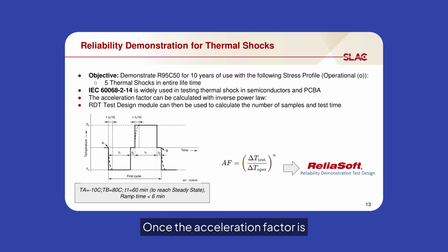Once the acceleration factor is defined, the reliability demonstration test, RDT, design module is used to determine the required sample size and test duration needed to quantitatively demonstrate the target reliability and confidence level.